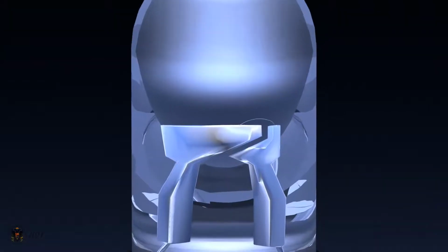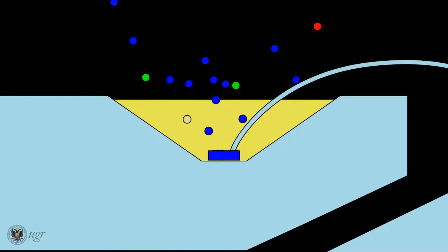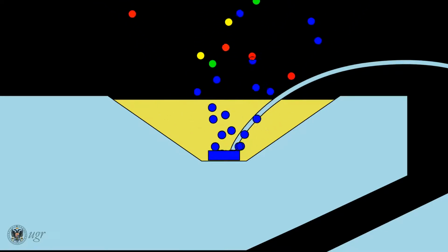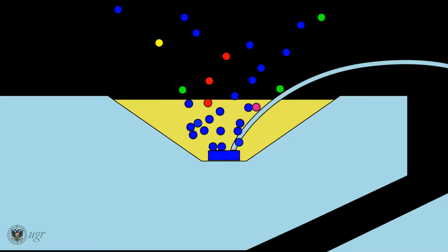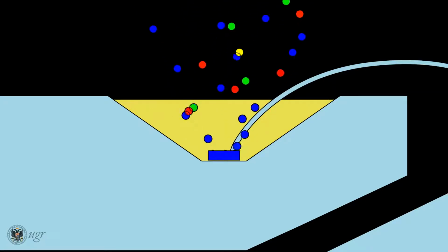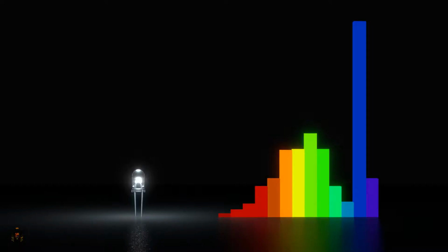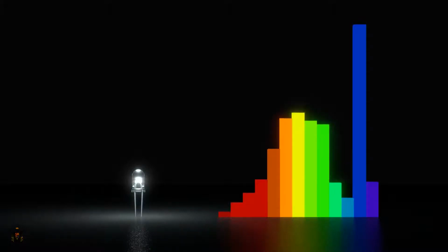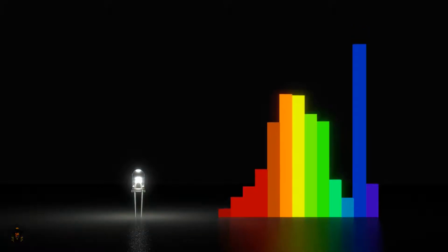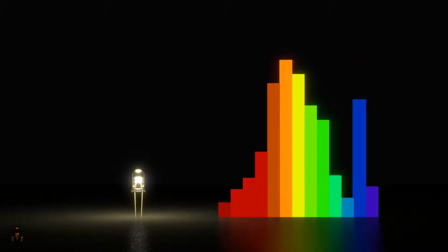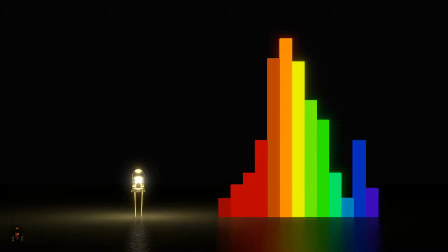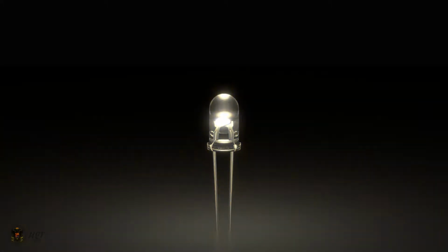Currently, the majority of the LEDs used in lighting are based on a blue LED coated with a fluorescent substance. This absorbs some of the blue light and re-emits it with longer wavelengths. The mixture of photons leaving the device is white light, which may have a bluish or yellowish hue if higher or lower energy photons dominate respectively. This depends on the well-known device color temperature.